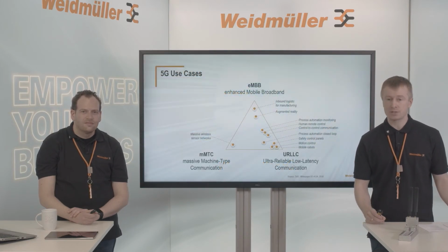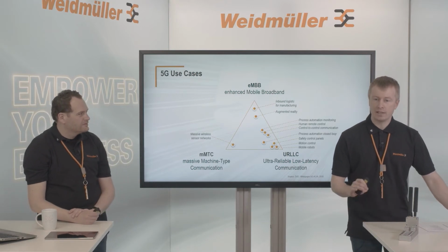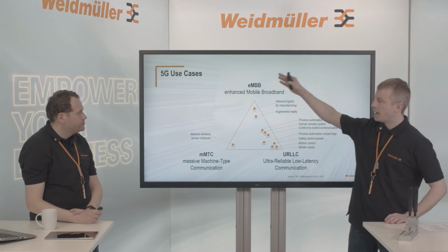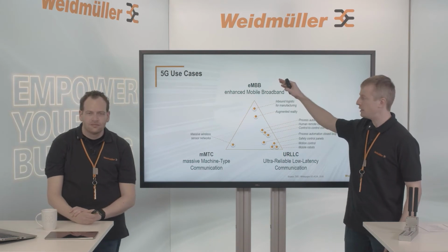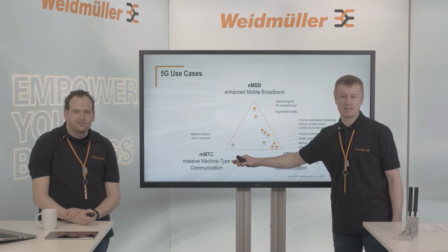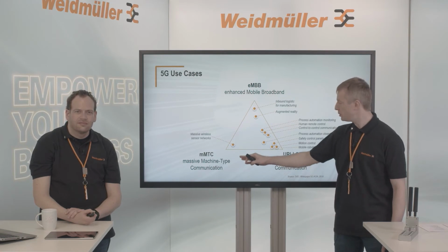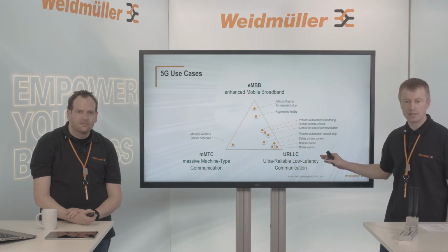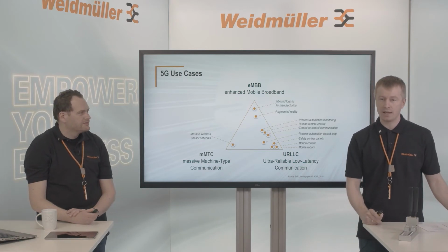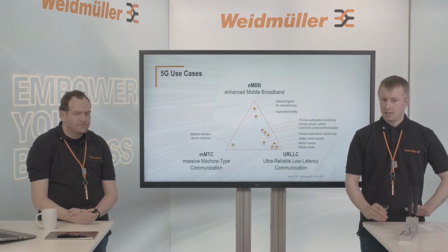5G is not only focusing on high data rates. It is focusing on 3 different clusters of use cases. Here it's shown in a triangle. Enhanced mobile broadband, that are the high data rates. Massive machine type communication, the high device density, but also energy efficiency to operate sensors on battery for multiple years, and ultra reliable low latency communication, real-time communication with a reliability of 99.99%.